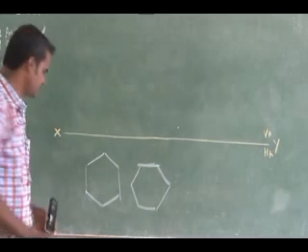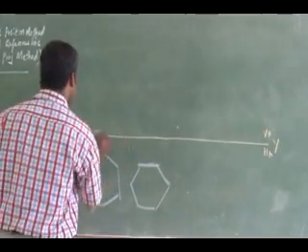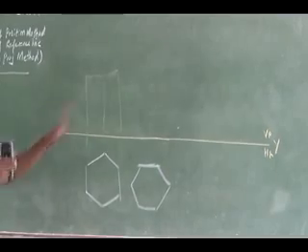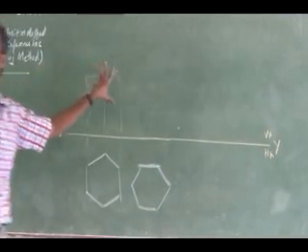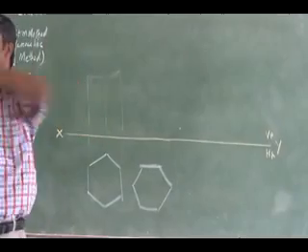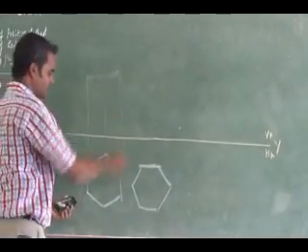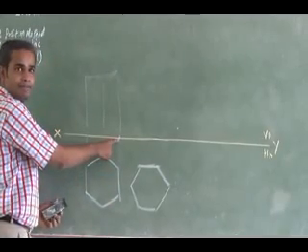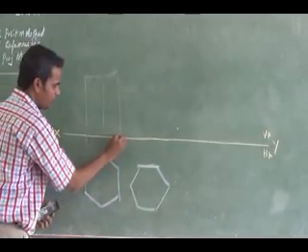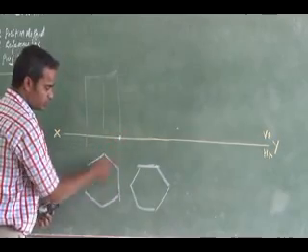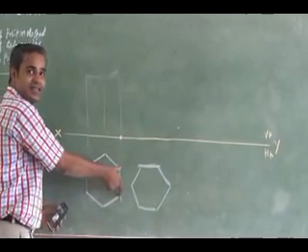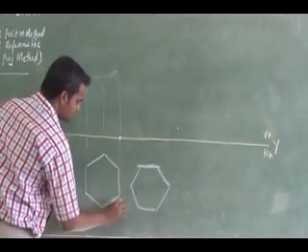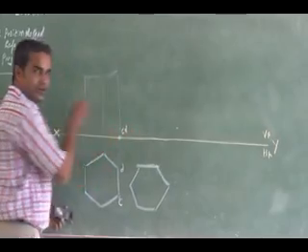So you see here, for the first step, I will be projecting the front view like this. Then I am going to tilt the front view, change the position of the front view to 30 degree. That is the change of position. So if I tilt, whatever falls here, is it edge or corner? Whatever projection I have in this front view in this location, it is nothing but the edge. Say suppose it is CD. The CD edge I will have here.